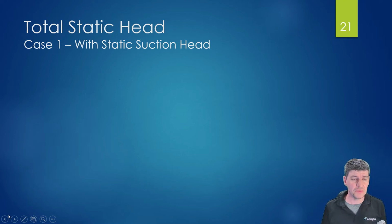If we look at our system where we've combined our suction head and our discharge head, then we can look at the total change of heights and come up with a total static head. And because we have two cases, where we have either a static lift head or a static suction head, we have two different ways that we can visualize our total static head. So let's look at it when we have suction in the first case.